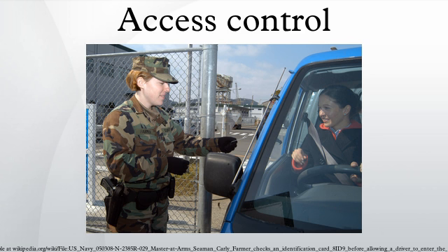To automate this, operator intervention is replaced by a reader. The reader could be a keypad where a code is entered, it could be a card reader, or it could be a biometric reader. Readers do not usually make an access decision, but send a card number to an access control panel that verifies the number against an access list. To monitor the door position, a magnetic door switch can be used. In concept, the door switch is not unlike those on refrigerators or car doors.